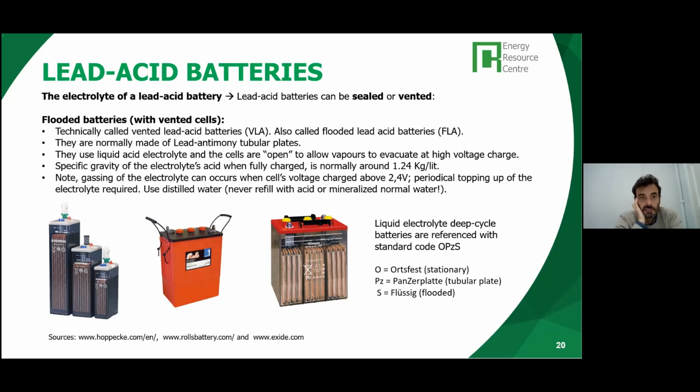So when these batteries are charged, the specific gravity, the density of the electrolyte, is around 1.24 because it's a mixture of acid and water, and the density, instead of being 1 for the water, is 1.24. So there's a lot of presence of sulfuric acid in the electrolyte. So refill with distilled water and not with mineral water.